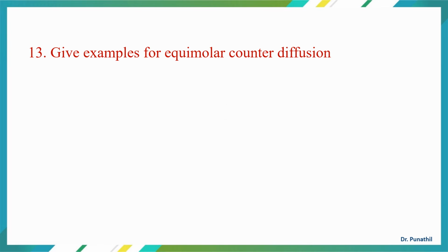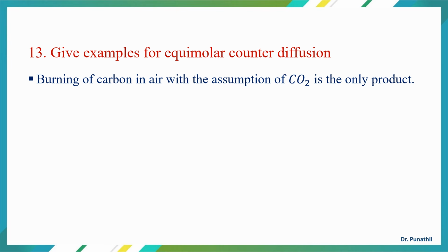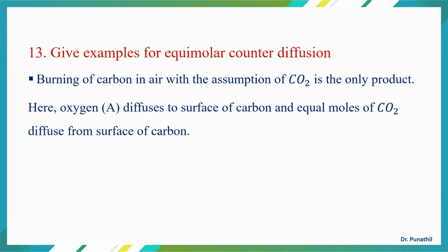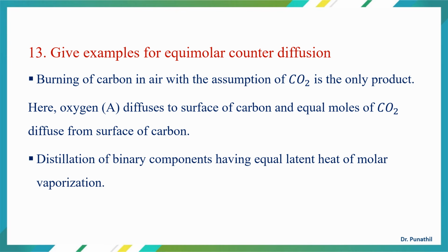Give examples for equimolar counter diffusion. Burning of carbon in air with the assumption of CO2 is the only product. Here, oxygen diffuses to surface of carbon and equal moles of CO2 diffuse from surface of carbon. Another example, distillation of binary components having equal latent heat of molar vaporization.